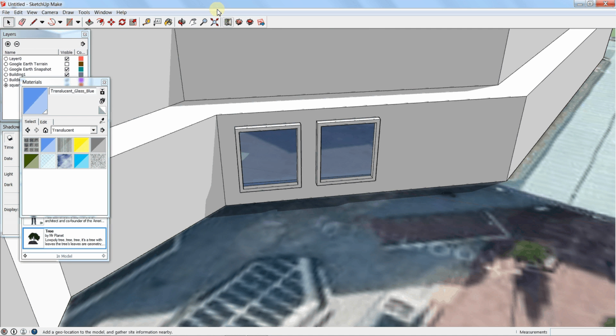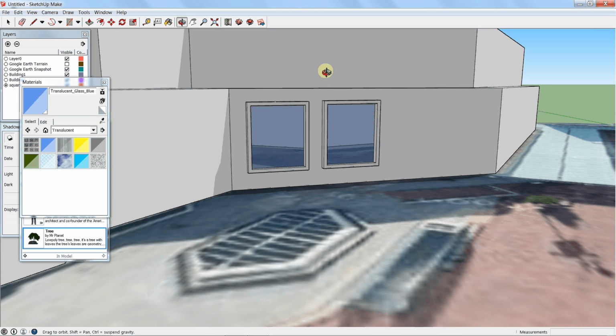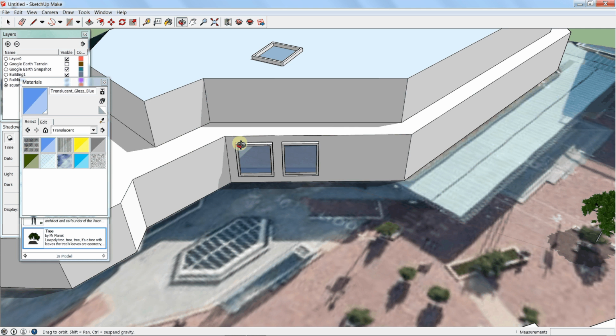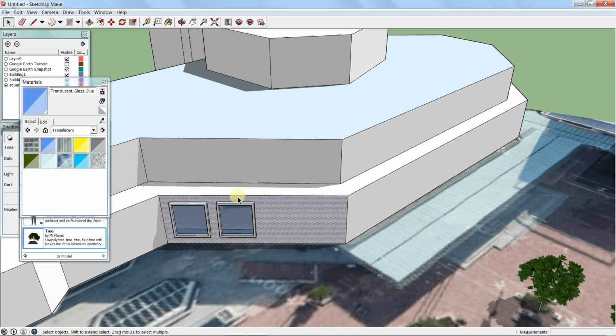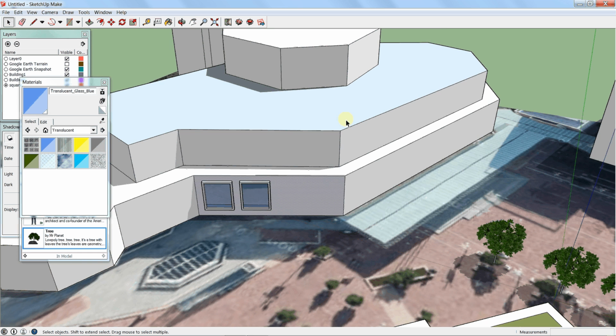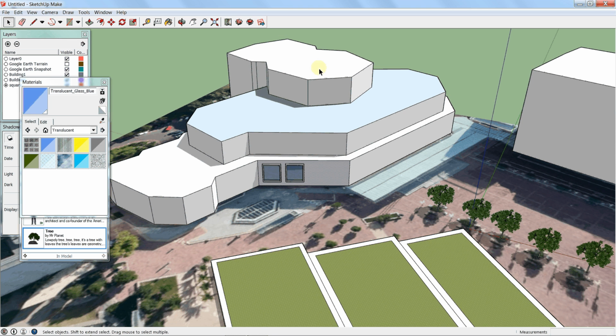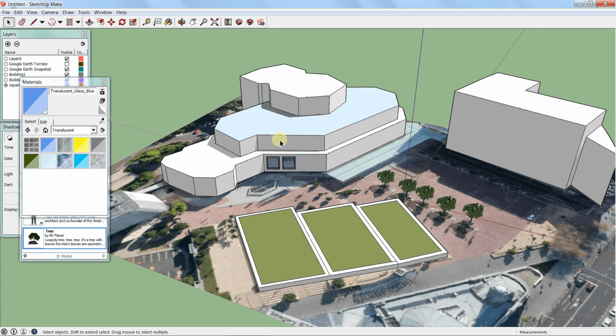You can see what it's doing here is it's allowing me to look inside the building. That translucency is in all the objects, including this one. We don't want that one there because that's a bit of a strange place for it, so let's just delete it. And there we go. So that is just some of the basic concepts. Materials, how we've got a selection of materials to use, how we can use set components, we can create new components, we can structure it on layers and turn things on and off, and we can also geolocate our model in the world.